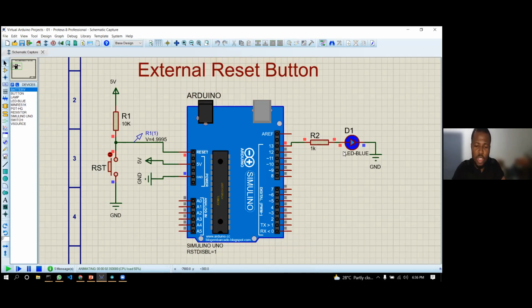It is just responding to the program that I wrote, just like an actual Arduino. Again, this LED is connected to pin 13. So even if you are following, you can just run the code, and on your normal Arduino, you should see the LED on the board blink. Now look at what happens when I press the reset button. You see that the whole program started again.